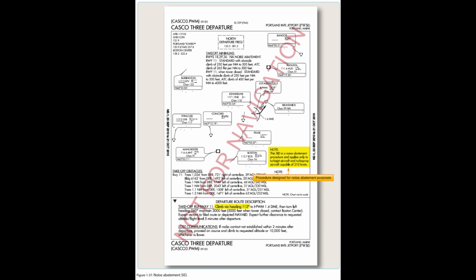Runway heading is the magnetic direction that corresponds with the runway centerline extended, charted on the airport diagram, not the numbers painted on the runway. Pilots cleared to fly or maintain runway heading are expected to fly or maintain the published heading that corresponds with the extended centerline of the departure runway, until otherwise instructed by ATC, and are not to apply drift correction, e.g., RWY 11, actual magnetic heading of the runway centerline 112.2 degrees, fly heading 112 degrees. In the event of parallel departures, this prevents a loss of separation caused by only one aircraft applying a wind drift.